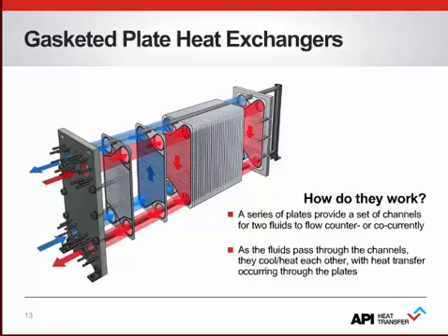There's typically the hot fluid going from the top to the bottom, and the cold fluid going from bottom to top. The reason that the cold fluid goes from bottom to top is simply that in case of evaporation, the gas phase would go upward with the flow of the fluid. Every second channel contains the same fluid.